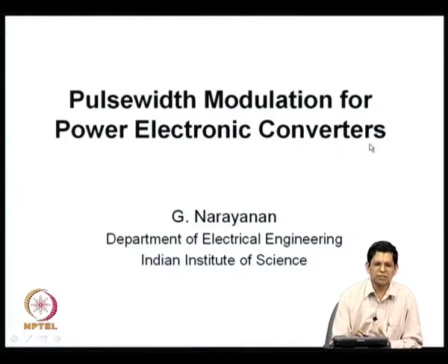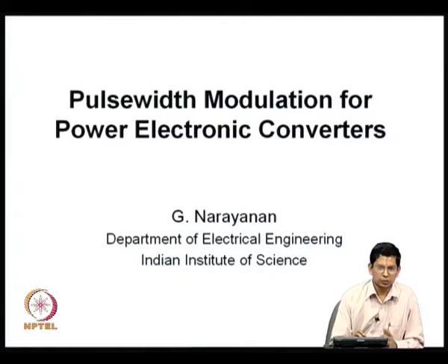We should have heard about several converters such as DC to DC converters, that go by names like step down choppers or step up choppers, and voltage source inverters, current source inverters. All these are various kinds of power electronic converters. You use them to convert, let us say, DC into AC or AC into DC, or DC of one voltage level into another voltage level, or AC of one frequency to be rectified into DC and converted back into AC of another frequency.